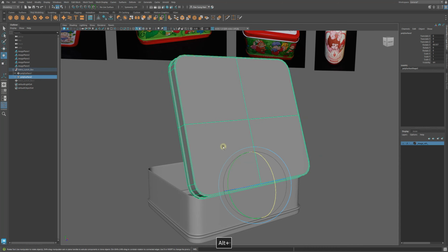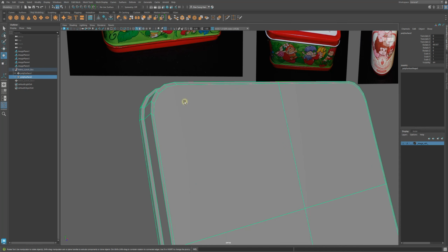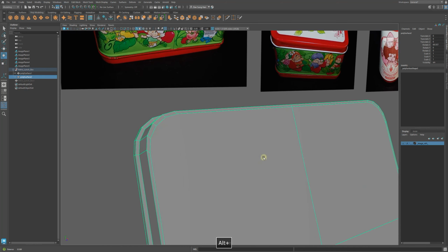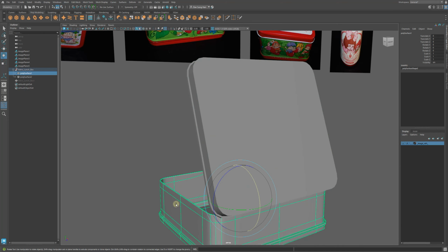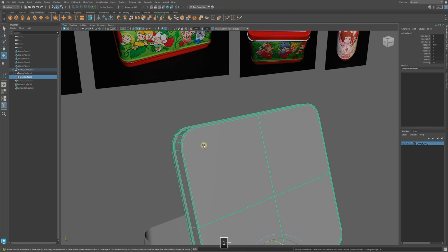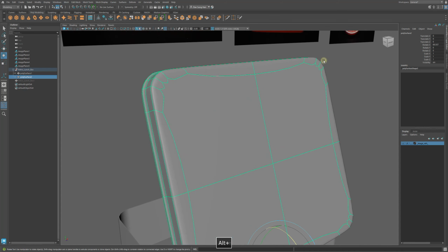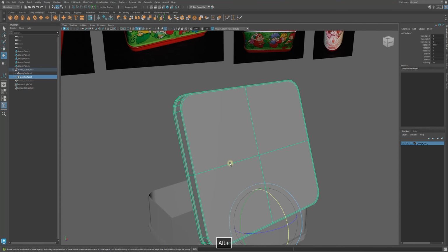And then this stuff still has to be refined, because these are what you call open edges, open faces, more than 4 faces. These have to be made into either triangles or quads, 4-sided shapes, which are fairly easy. They're required for games in general, for smoothing your object, and for what we call texture mapping, because this will cause stretching, where when you do the projection, the image will skew and stretch potentially a lot.